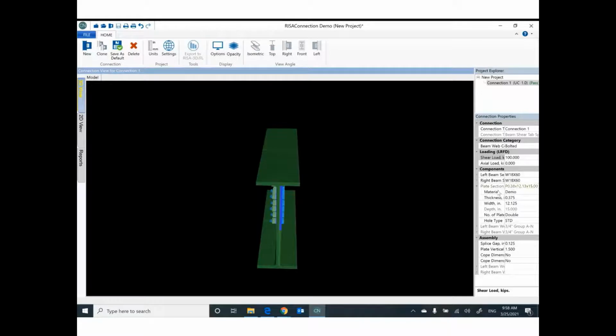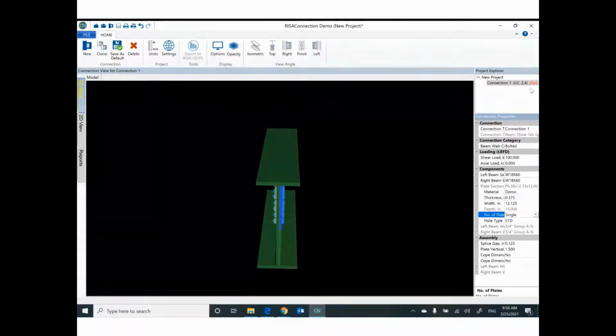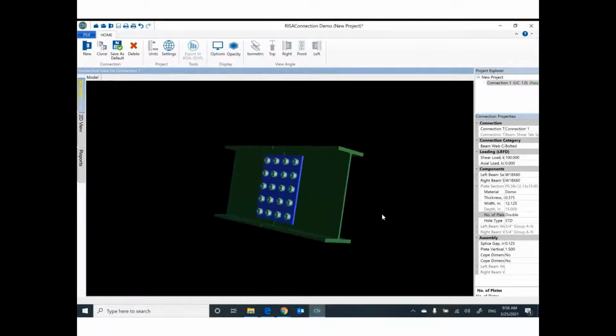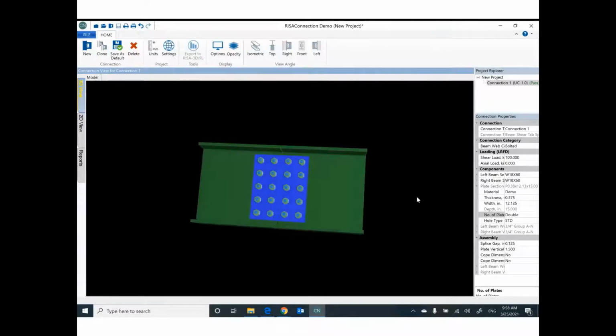You know, if we go back to the blades and make it a single blade only, it fails. The connection is not safe. So if you have this level of shear, 100, we need to make this blade double to be safe. So you are doing many trials until your connection is safe against your applied load based on the structural analysis. Then we are done.